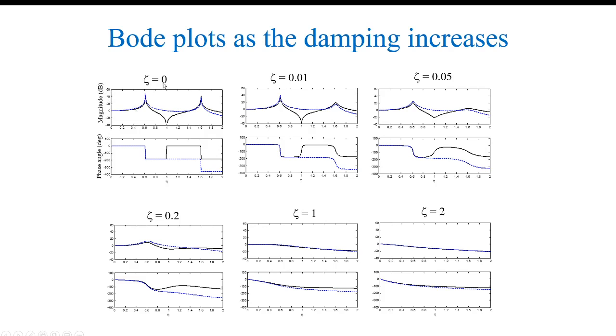I mean, when zeta is equal to 0, they blow up. The reason why you don't see it going to infinity is that these two peaks are the two natural frequencies, and they should blow up. You don't see it because it's MATLAB and I'm sampling at, let's say, every 0.1 eta, so I never actually get infinity, because I'm not really sampling right at the natural frequency.